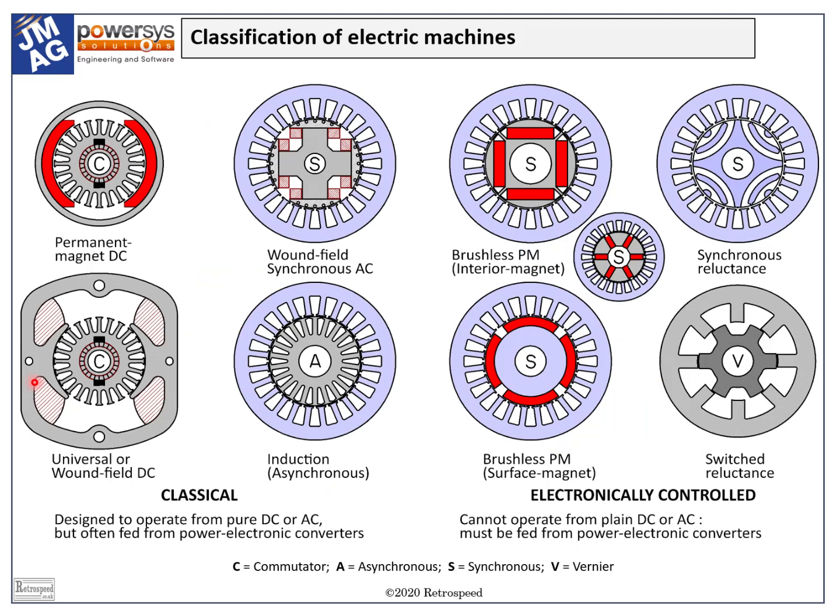It would be very desirable for all of the control features of the wound field DC motor to apply to the AC machines, the blue ones, and especially the induction motor, which is nowadays the mainstay of variable speed drives in larger sizes, and equally to the permanent magnet brushless AC motors in smaller sizes.